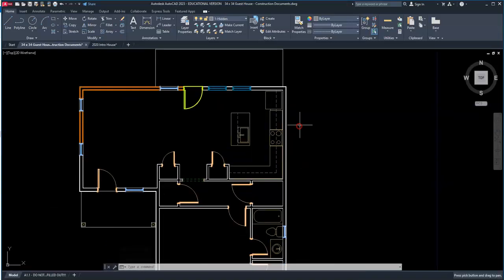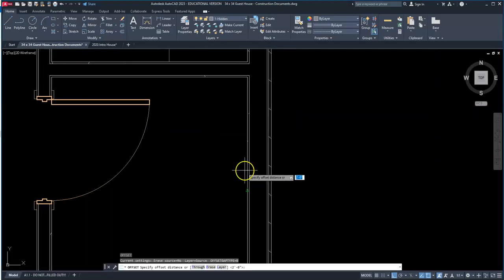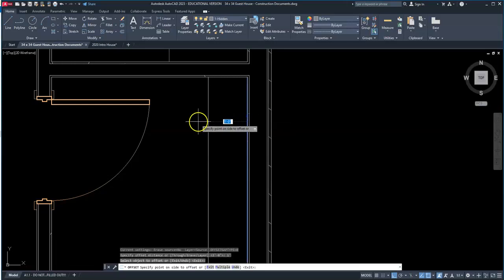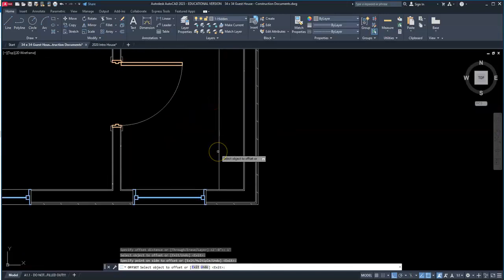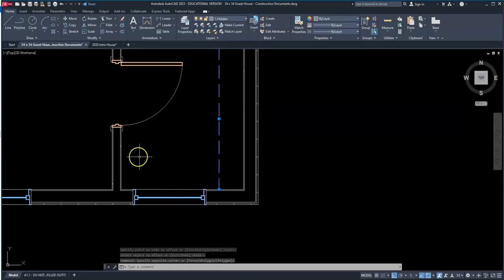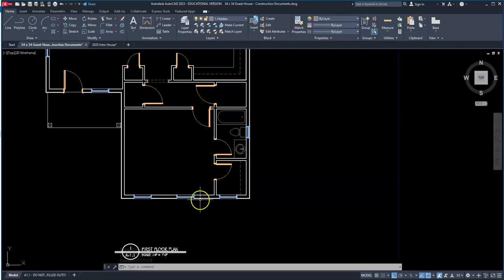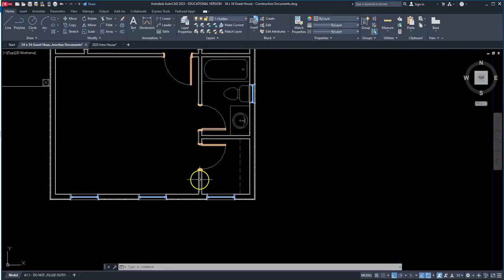and that moves my hidden line up. And then for the closet, same thing, we're going to offset again. It's going to be 1 foot away. Change the layer to hidden. Now you might be thinking, well, how come we didn't put a line offsetting here for more shelving space? We did not do that because of the window. This window was placed here for the pattern to be 3 equally spaced windows. So we will not include a shelf in front of the window.